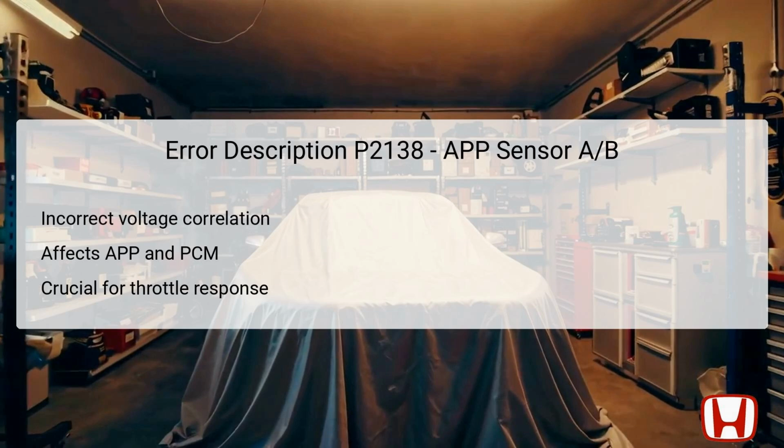If there is a malfunction, either due to wiring issues or sensor failures, the PCM will not receive accurate information regarding the throttle position. This can result in poor engine performance, erratic acceleration, or the vehicle entering a fail-safe mode. The DTC will be recorded as either confirmed or pending based on the failure mode observed during diagnostic checks.